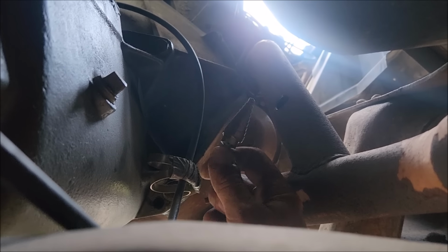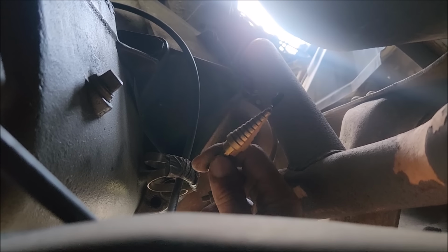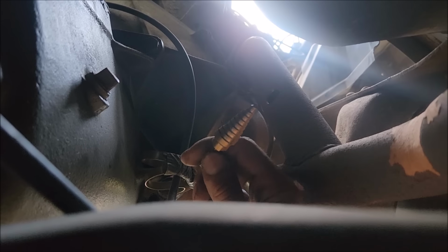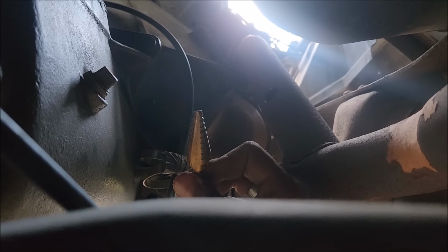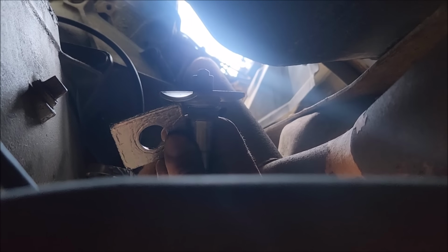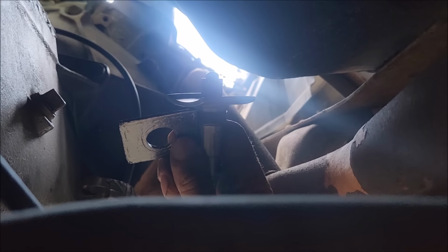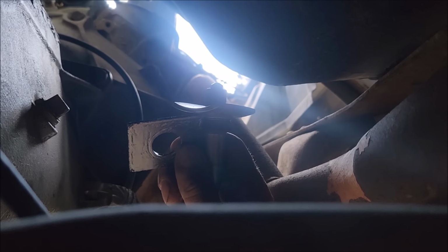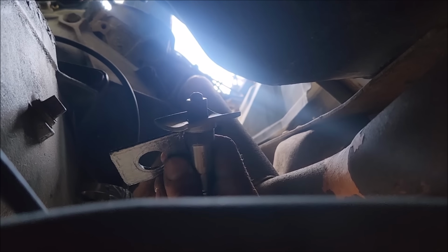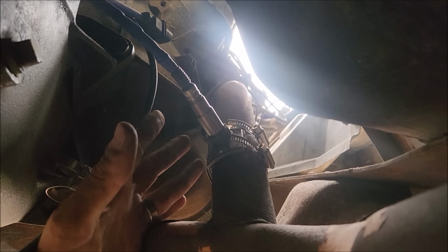All right, and as you can see there, we got a good hole in the exhaust with our step bit. You want to make sure you don't go all the way through one side and through the other, depending on what size step bit you use. This was a 3/4, and it worked pretty good. But yeah, step bits, probably the best invention since, I don't know, cheesecake or something. So with that, I'm going to get our wideband installed here. It's a good idea to put your clamp-on adapter in a vise and spin your wideband O2 sensor into that before you go to install it, which I've already done here. All right, so with that, the wideband O2 is all installed, and you can see it's pretty easy to do.